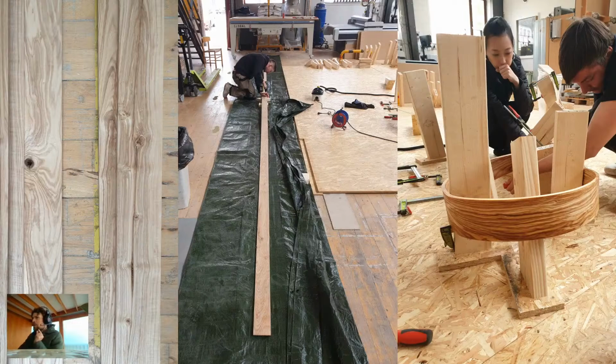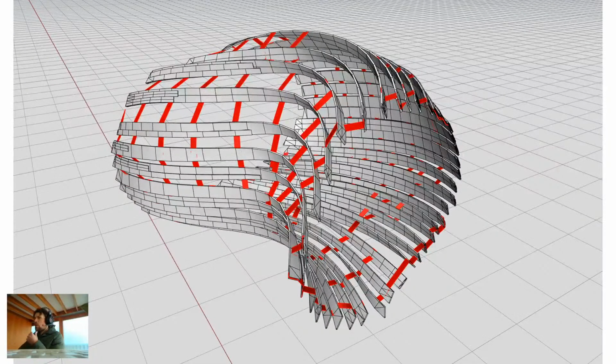And so we ended up building this pavilion from floppy material. So we're not making it from rigid material at all. It's almost like putting together a piece of a pavilion from a whole lot of spaghetti that just flops around until you pull it into the right shape, using this kind of composite shell of these weak timber strips and weak steel elements that I'll show you in a second. And so because you're constructing from something which is really, really floppy, this just would not be possible to construct in any other way without having literally a mold or a framework for every single part in the structure, which would be far more costly than the part itself.